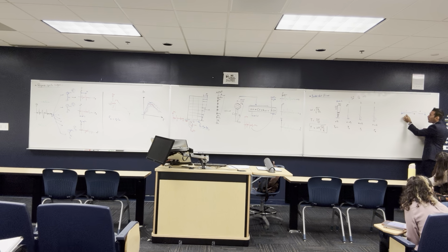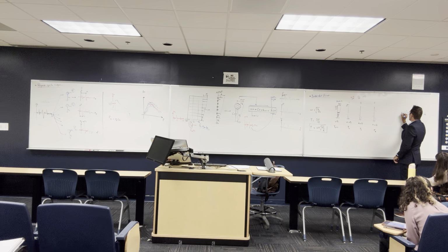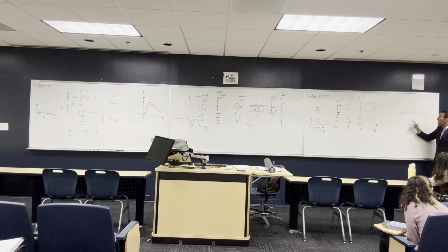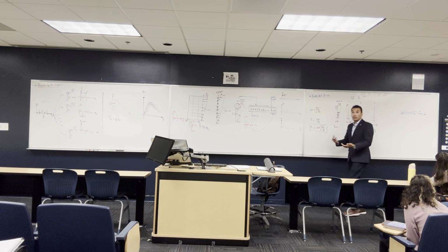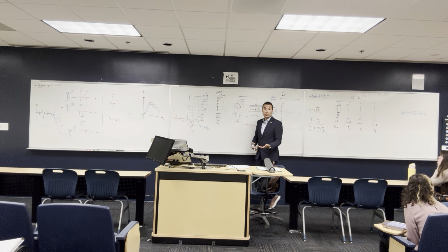So the more you go to the maximum bending, you will find more reinforcement. So they make many cuts. Some reinforcement goes from here to here, and then here you don't need that much reinforcement. You don't need all that reinforcement to go all the way from here to here, because here the moment is almost zero. There is no tension. So basically you make fewer cuts so that you can save on reinforcement. All this stuff you can learn in the reinforced concrete class.